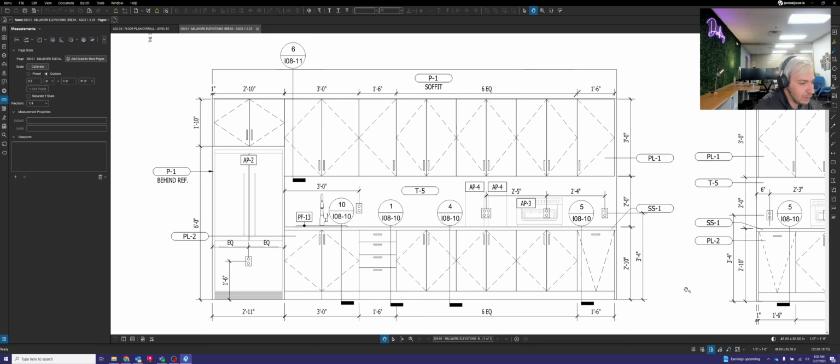What we're really going to be focused on is the finish of the cabinets. As I'm looking around this elevation view, I'm noticing right here that these upper cabinets are called out as plastic laminate 1. And it looks like these lower cabinets actually have a separate finish. These are plastic laminate 2. So we have to be careful about that. We can't just label it all as PL1 or it'll get made with the wrong finish, and you don't want to deal with that. Just keep in mind, these are 2 different plastic laminates on the job, and we'll look at those in just a sec.